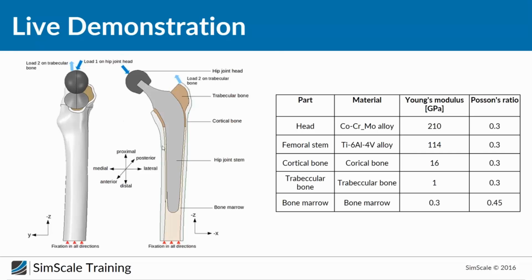But what we've done here is we divided the bone into subsegments which have constant material properties, and there we can use this approach. For sure, it's not 100% exact because it's not linear elastic, but its approximation is good enough for reality.